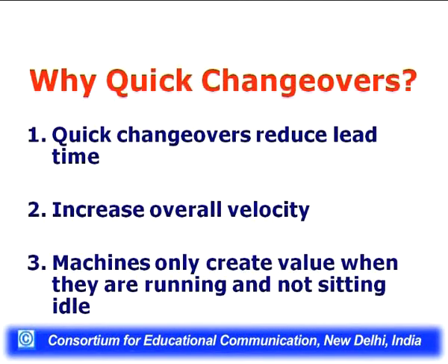Why quick changeovers? Quick changeovers reduce the lead time. Lead time is the time required to give a new product to the market or to the customer, and quick changeovers increase overall velocity. If we reduce the changeover time, overall velocity will improve. Machines only create value when they are running and not sitting idle. We want the machine to be running all the time, because a running machine will give us a manufactured product, not a stopped or idle machine. So the changeover time, the setup time should be minimum, because in this period the machine is not producing anything.